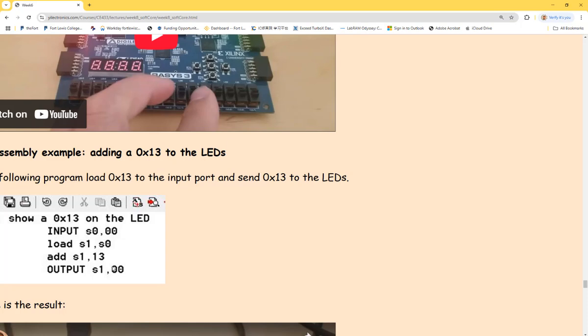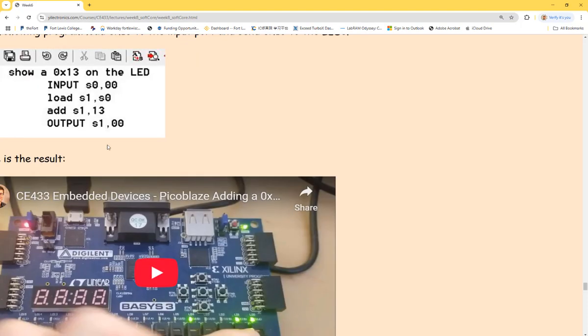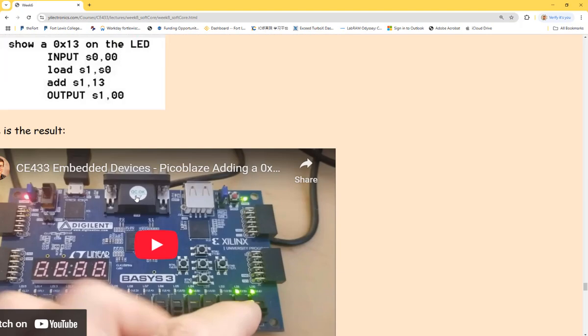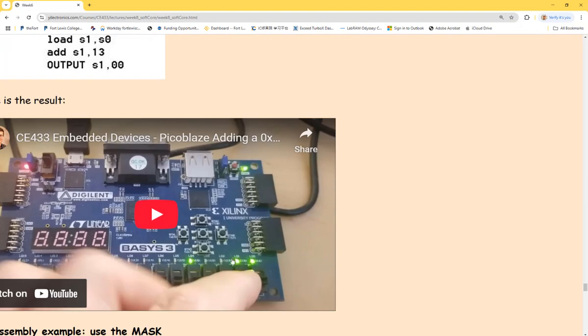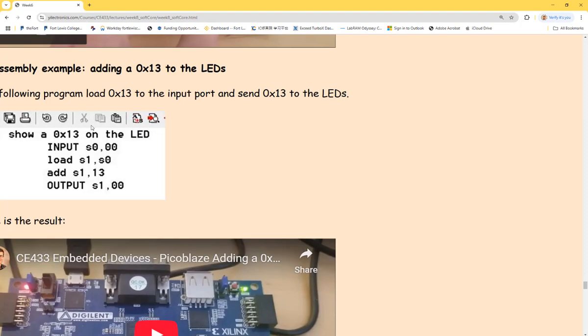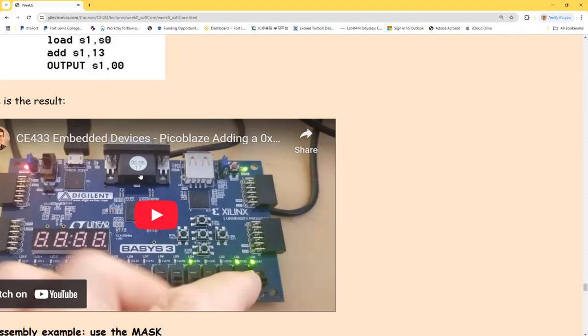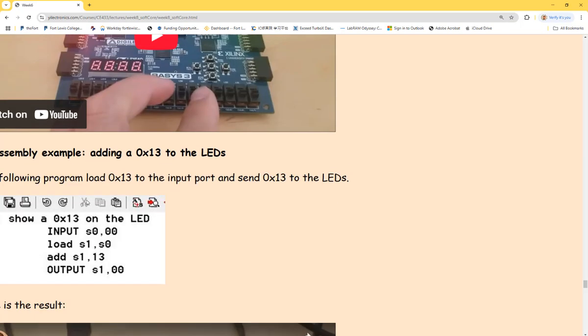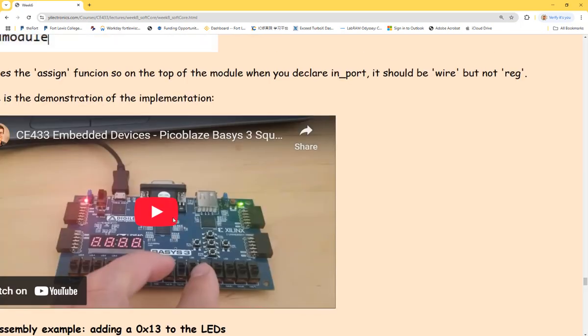It's an output port, but the address for that output port is 00. So there are another 256 output ports with the microcontroller as well. This is sent to the output ports, and eventually you connect these output ports to the LEDs in your Verilog, and all this code is provided. The first example will help you understand what's really going on here.